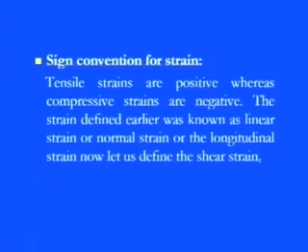Then the next point is the sign convention of the strain, irrespective of whatever the loading is. As we discussed, I just want to refresh this: whenever there is tensile pulling, tensile load, or tensile stresses, they are always termed positive, and compressive stresses are always termed negative in the normal stress form. And for shear stress, if the object is tending to move in the clockwise direction, we use the positive sign, and if it is tending to move in the anti-clockwise direction, we put the negative sign.